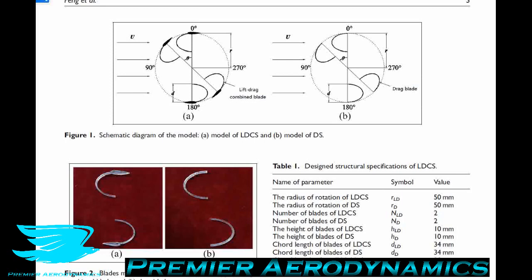This will only happen when the blades have rotated and are now pitched at an angle to the oncoming flow, and hence these airfoils attached to the blades will produce this lift that we need. So we have these airfoils here now, and the air comes in. You can see that the angle of attack is now non-zero, and this will now produce some amount of lift.